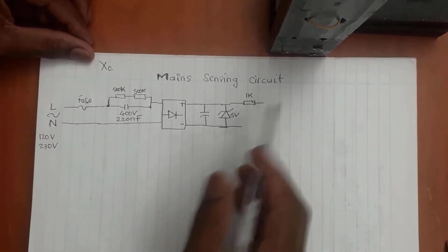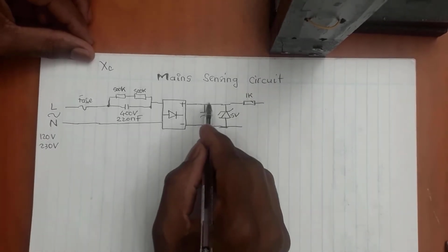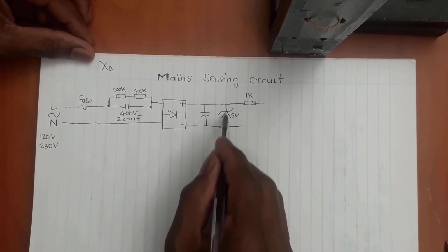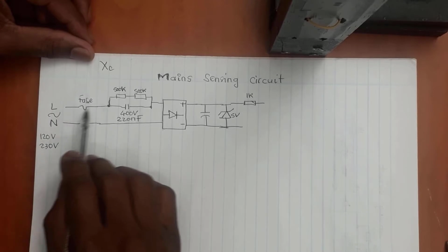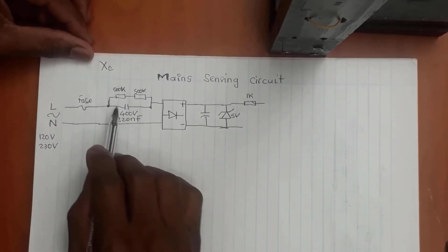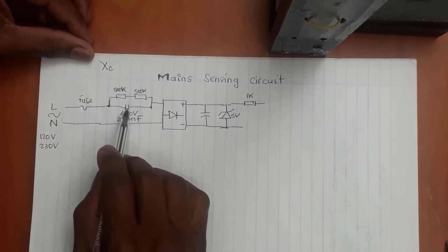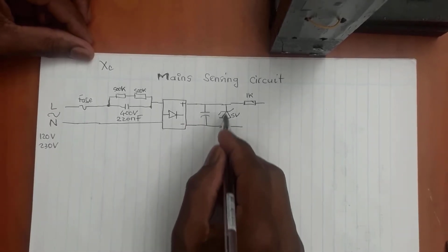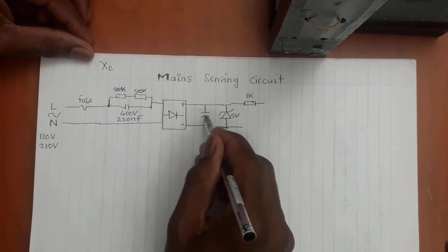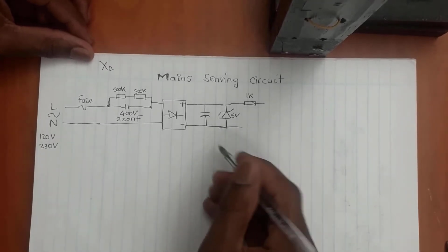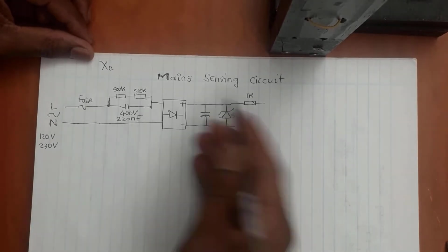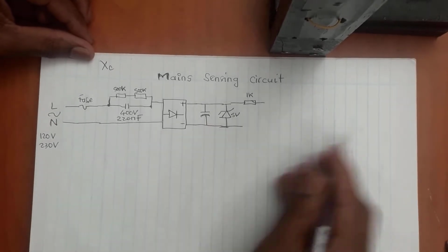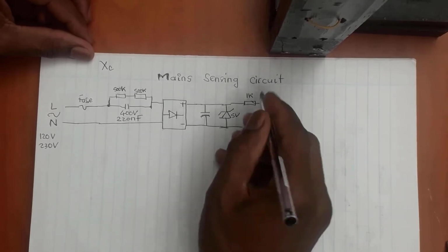Now, many of you might be asking, why is there no resistor here to limit the current going into the Zener diode? Because there could be an inrush current once you connect AC, because the capacitor will try to pull as much current on the first time constant, and all of that current will come through here. Also, based on this capacitor, the Zener diode might break if it's not rated higher. But for design's sake, we can put a resistor, but I'm leaving it out here.